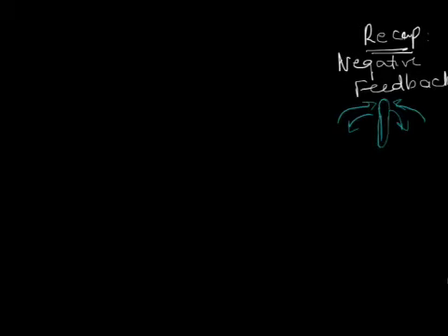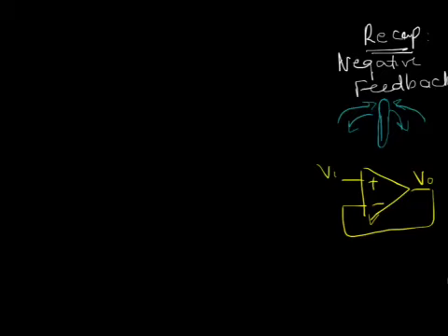What does this mean in terms of op-amps? Is that we expect, like if Vout is supposed to remain at a particular value, when we feed Vout into the negative terminal, after that, if Vout increases, then this value increases and that will pull VO back down. While the other possibility, if VO decreases from its ideal value, this value also decreases and that pushes VO up. So if at all VO moves away from the value it's supposed to be at, the system will pull it back into its original state.